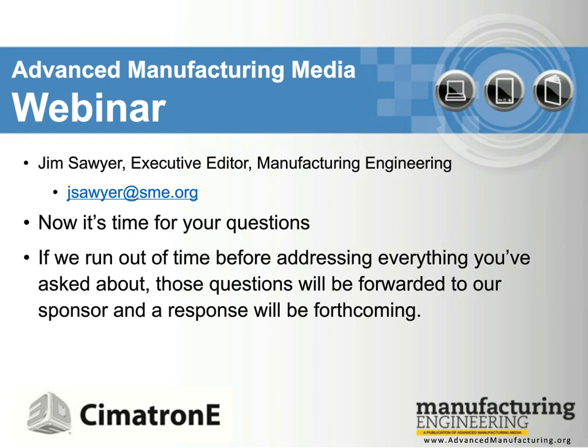Okay, and moving on: why do you prefer to put your electrode UCS on the tip of the trode instead of the base of the electrode holder? What benefits do you see with your strategy? That's an excellent question. My answer would be that I don't. I think the electrode UCS should be on the back of the holder because it's common for every electrode.